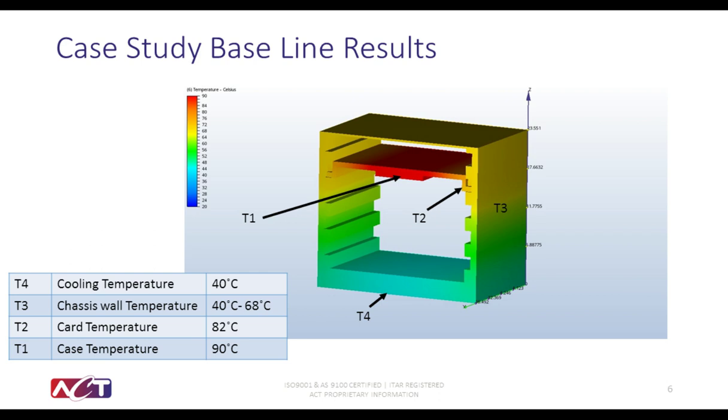The next critical point is the wedge lock. A standard wedge lock will have nearly 80% of the heat going directly through the card frame to the chassis. Only about 20% goes through the wedge lock. This creates a large temperature rise and a relatively short thermal path.